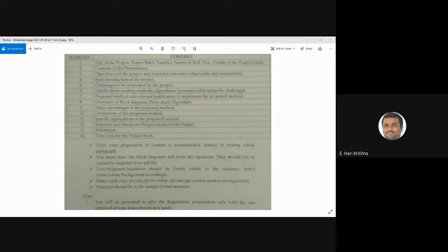And the important problem associated with the PPG signal is motion artifact. We call it noise because of voluntary or involuntary movement of the finger. Generally we may place the PPG sensor on a finger, earlobe, or some other part of the body, which can be read from the literature.